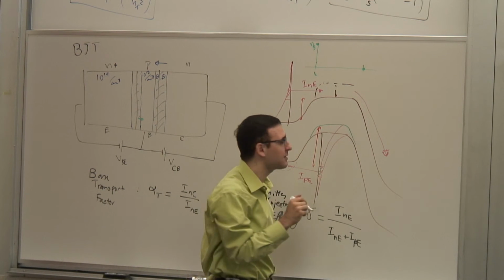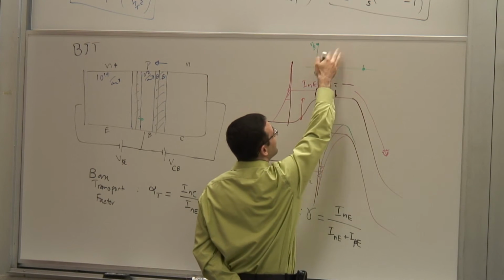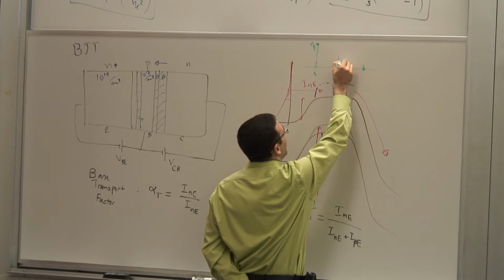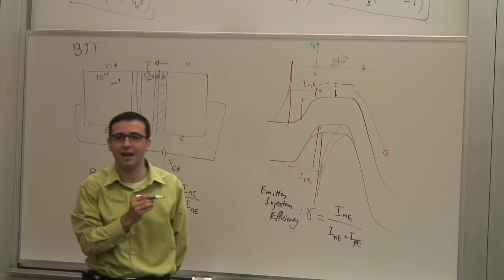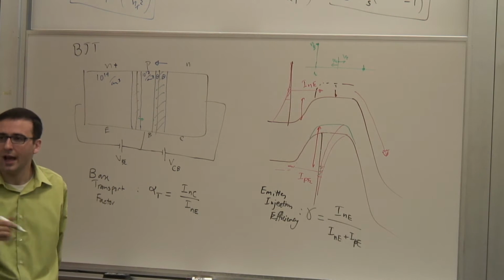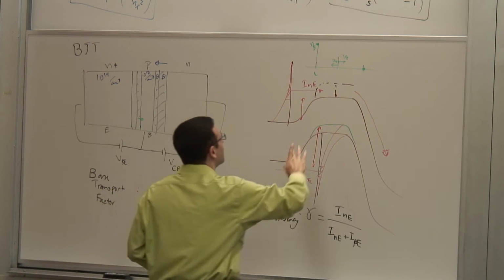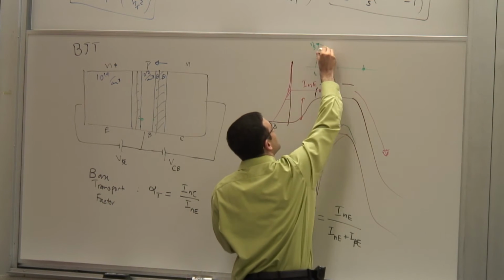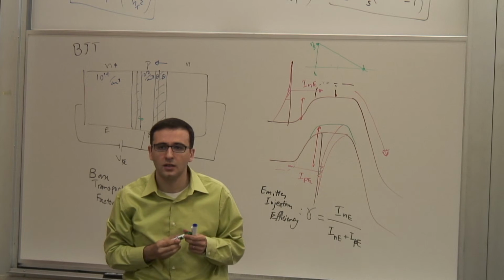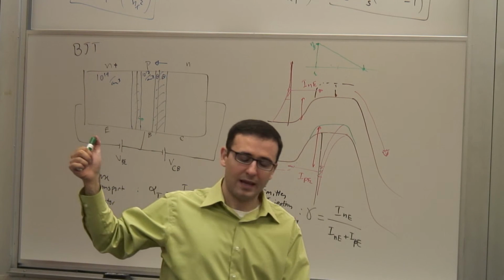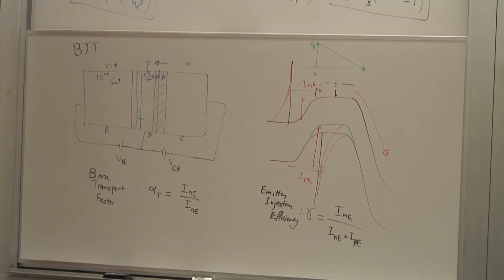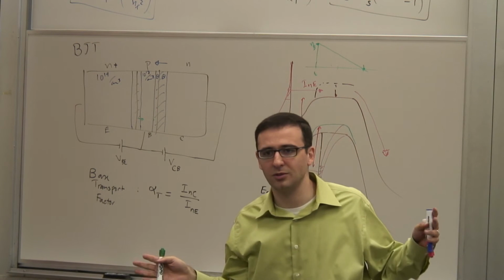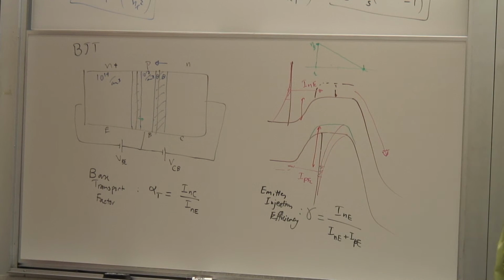And the other thing is that you assume that at any point you can have a random distribution, but there's a 1/2 probability of the electron going to the right, and 1/2 probability of going left for every electron. And you let it run, and you see very quickly it converges to something like this, which is not that surprising because it's a so-called diffusion process. So the electron concentration goes from the maximum to 0 linearly over this distance, and that's just purely because of its random thermal movement in the simplified picture. Okay?